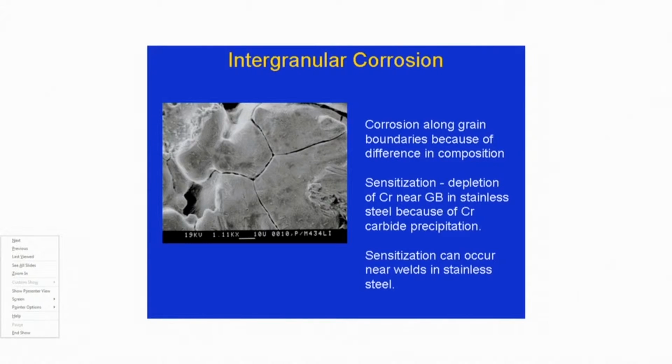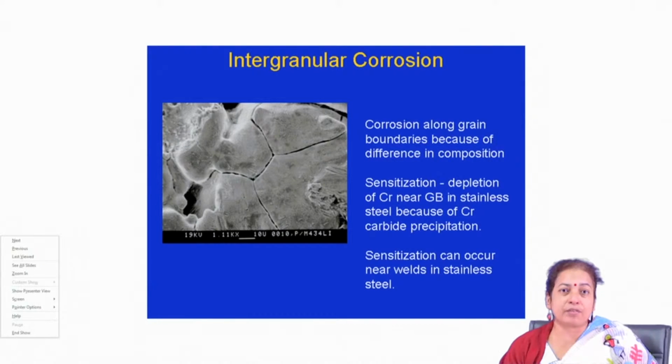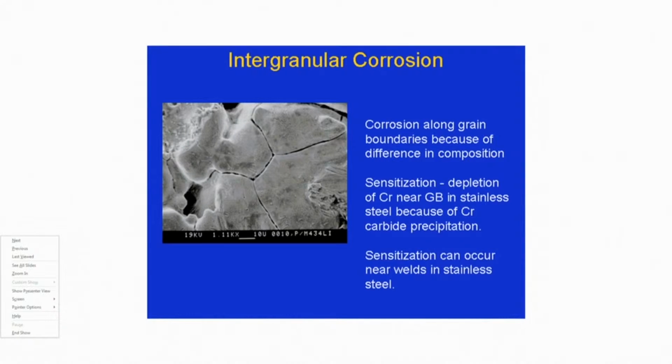If you talk about grain boundaries and grains, you will find that grain boundaries have a little higher energy than grains. So, usually the corrosion rate or attack rate of grain boundaries is much higher than that of the grains. That is why we see it etched when you view the microstructure of any component. But you have to understand that in pure metal the area fraction or volume fraction of grain boundaries is a little higher than that of grains, but not so high as to have an effect on the overall corrosion rate of the component.